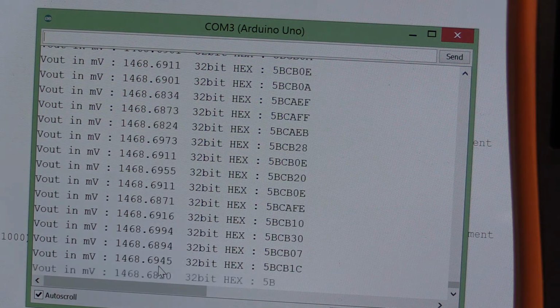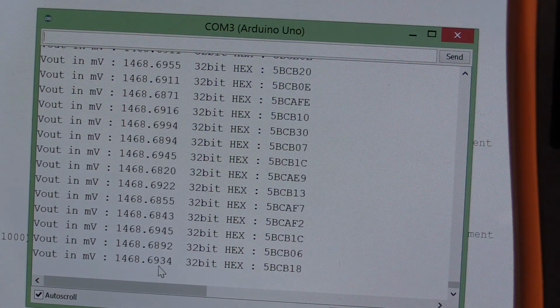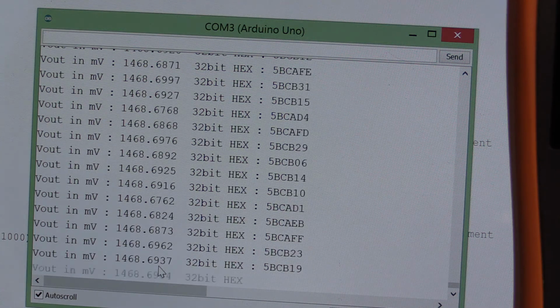With a bit of software compensation and things like that, and allowing for the fact that once it's in a power supply and not on a breadboard, it should be even more stable. You're probably easily going to be able to maintain certainly much better than 0.1% resolution. That's nowhere near what 24-bit is capable of, but it's going to be more than enough for the power supply.